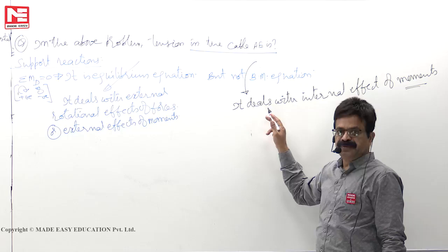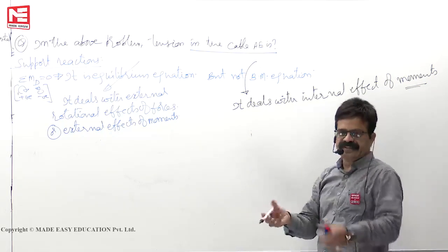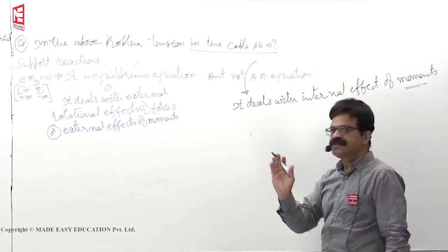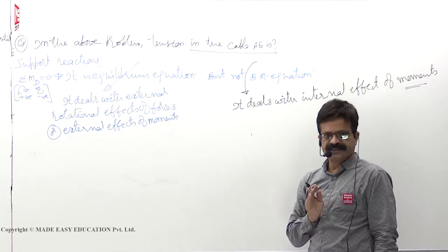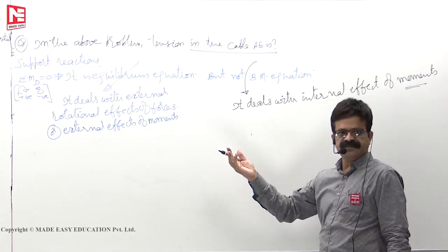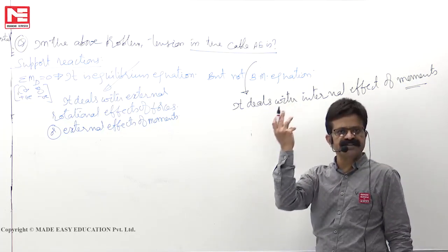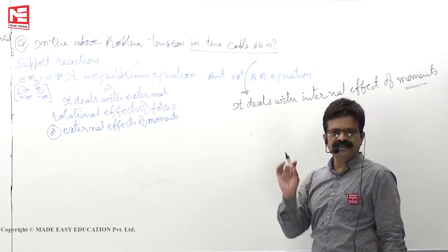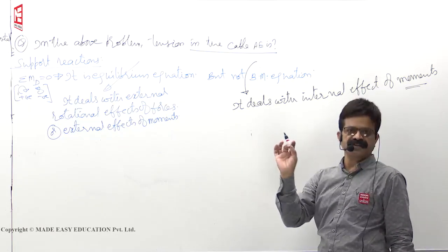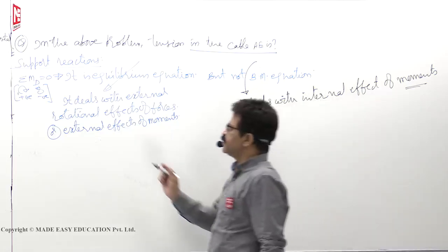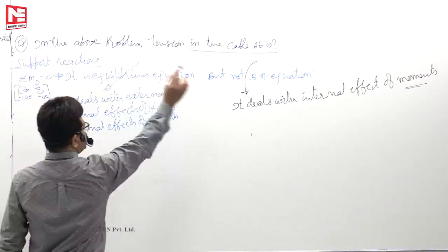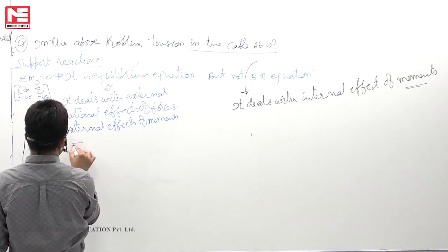But when you take the bending moment equation, you will know whether it is sagging or hogging, because you will see only one side of the section. Both sides of the section you take, wherever you take in a structure, sigma M must be 0. Otherwise, about that point, the structure will rotate. That is the difference between sigma M is 0 and bending moment equal to 0.